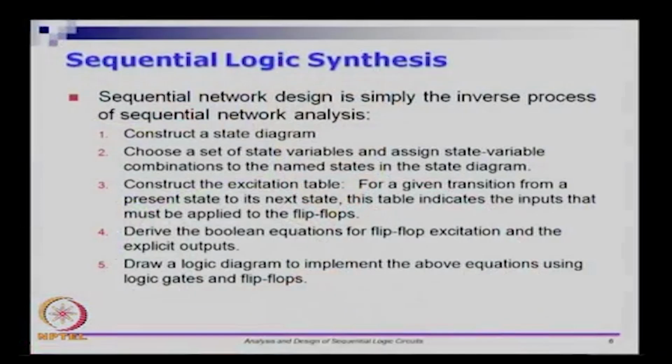So, this is called the synthesis problem, and the steps are actually straightforward, but it is the inverse process of analysis that we did earlier. In the analysis you ended with a state diagram, in the synthesis you start with a state diagram. You construct the state diagram based on the English description that is given to you. Once you have the state diagram, you go and choose a set of state variables and assign combinations to them. So, we will see an example in a little while, this sentence will make sense.